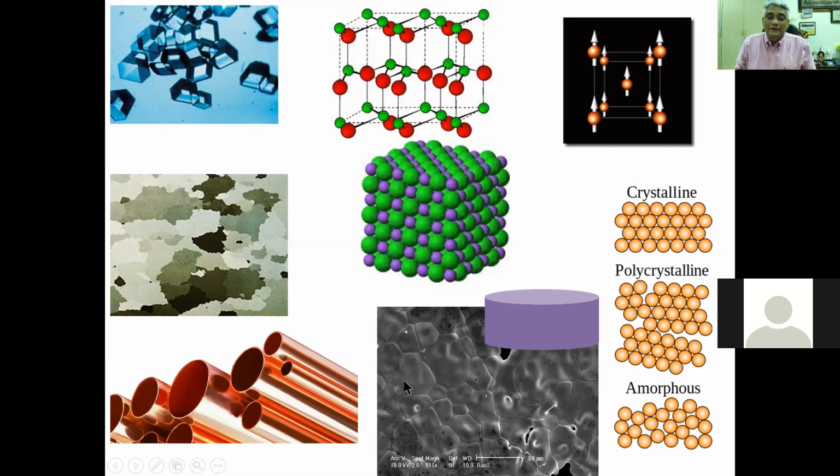So that means what? I told you, if I'm doing an electrical conductivity measurement where I pass a current through the solid, the current will go through the least resistive path only. Because at each point it has to surmount this barrier energy that is created by these grain boundaries. Okay, so if we need to do physical property studies on polycrystalline materials, if you don't have access to single crystals or thin films, the best option is to make sure that you prepare the polycrystalline material in a way that the grain boundary widths are minimized.